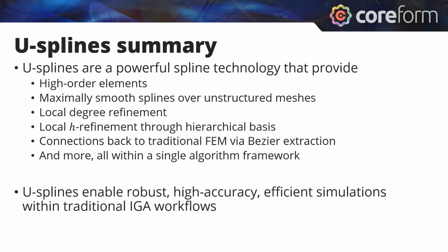So with that, I'll take a little bit of time to answer some questions if we've got them. One question is, with the smoothness available with U-splines, can they also model discontinuities? That's a great question. The answer is yes, they can model discontinuities just as any finite element code with C0 bases can. Again, we can switch down to a Bezier extraction framework, and if the discontinuity is, say, a crack opening, we can do all the same things you would do with a traditional finite element.